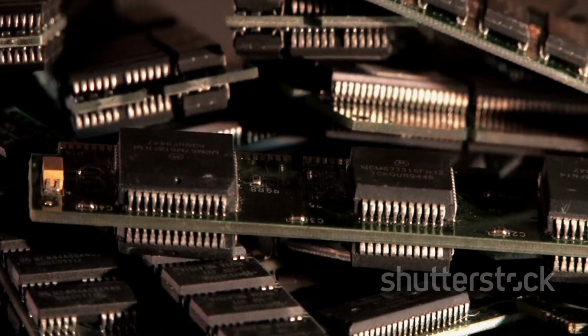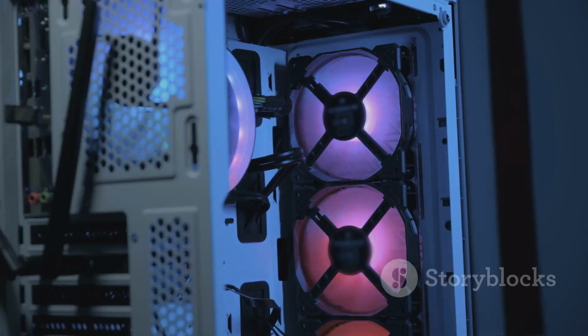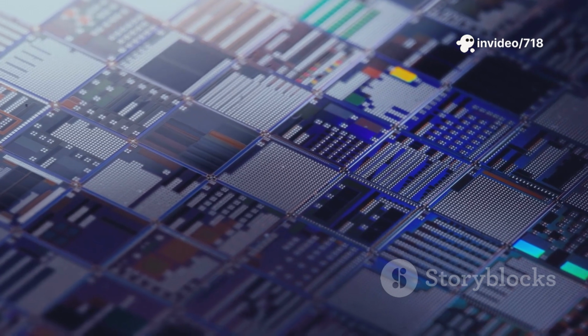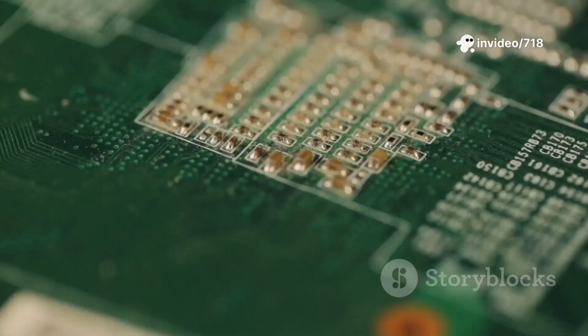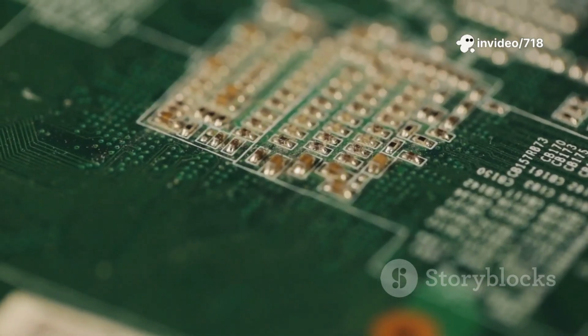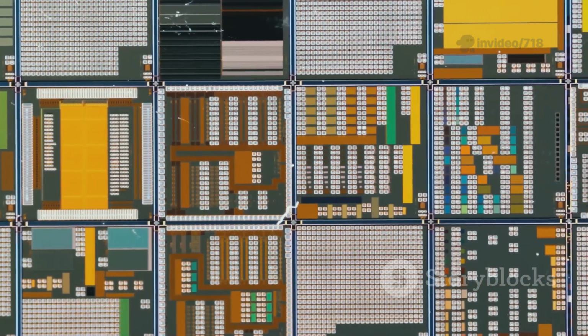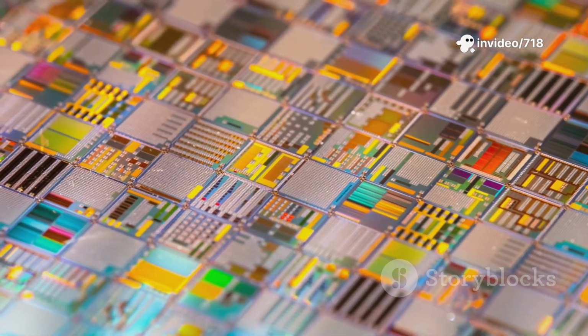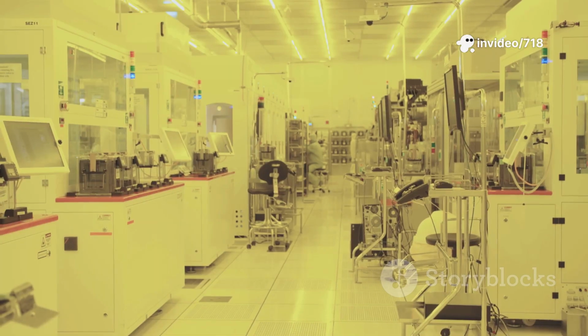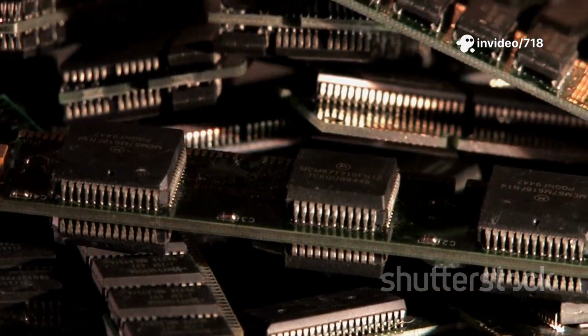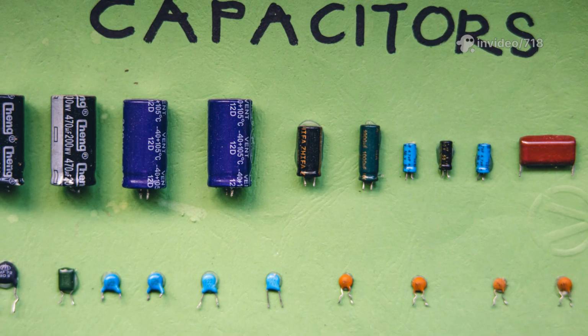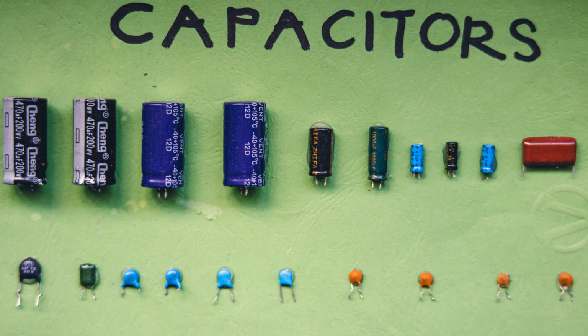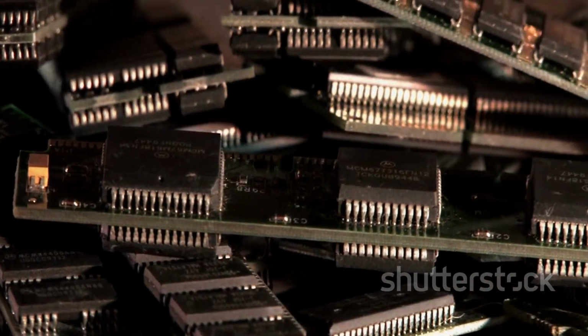The price per bit of memory fell relentlessly, making computers more powerful and affordable than ever before. This era of intense rivalry wasn't just about price, it was also about pushing the technology forward. The race to pack more and more bits onto a single chip drove incredible advancements in manufacturing processes, a trend famously captured by Moore's law. The competition forced engineers to come up with new cell designs, like the move from planar capacitors to more complex stacked or trench capacitor structures to keep increasing density.